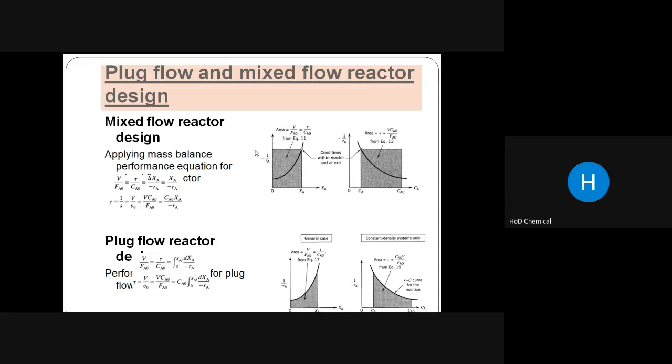The flow patterns do not occur properly, or there is time variation, like uniform mixing does not happen, or the flow from one reactant to another does not happen. Or one reactant can be stored in stagnant positions. All those factors we consider as non-ideal reactors.